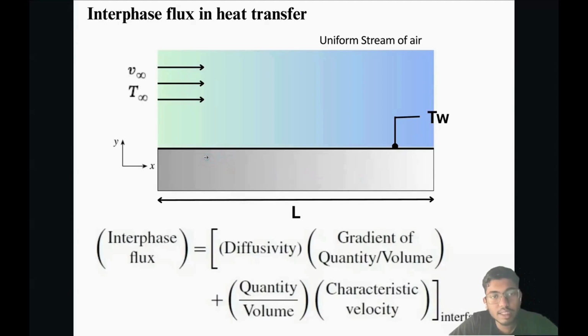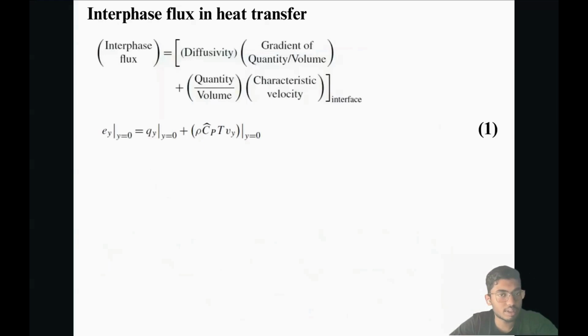So the layer of air just above the plate will experience some force, and it will not have the velocity which the upper layers of air have. So according to the no slip condition, there is no slip, that is, relative velocity at the interface is zero. That's why we consider the first layer velocity to be zero.